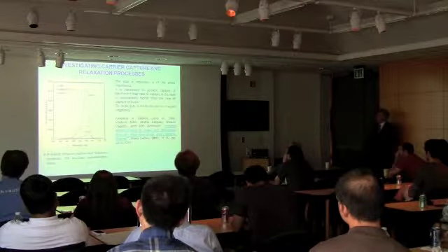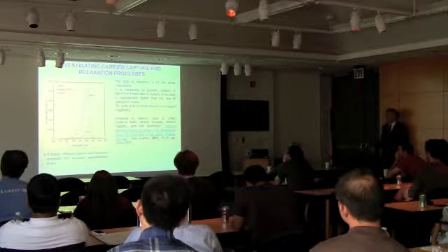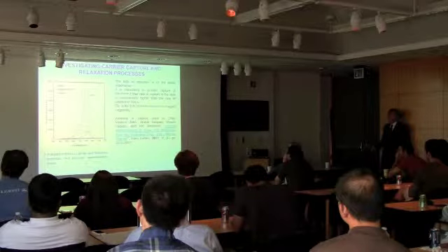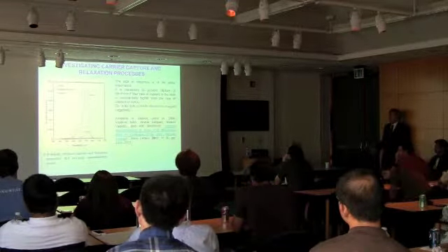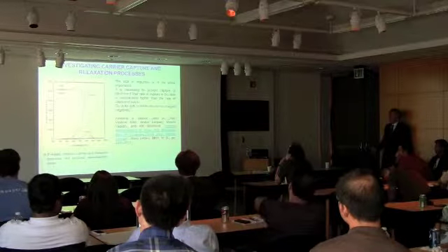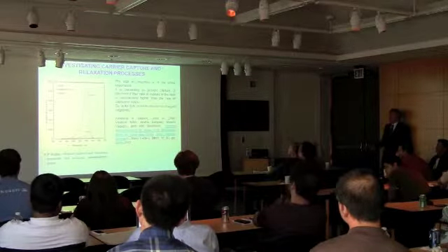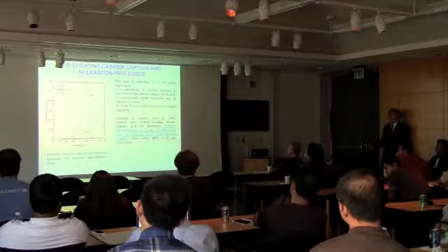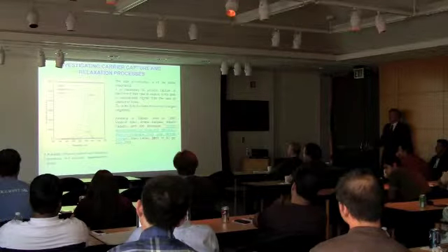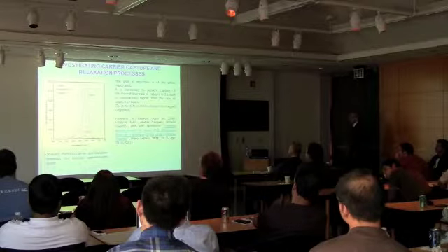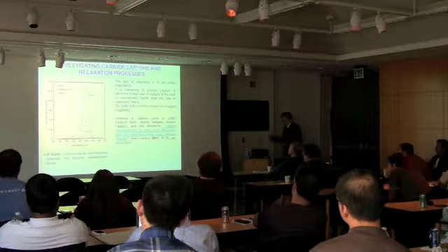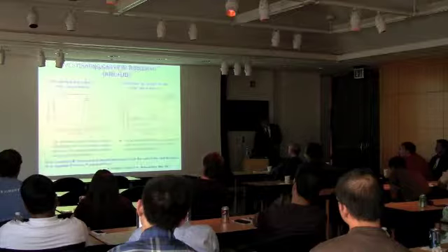Here it's the same level of doping. Exactly, we introduce 3 electrons or 3 holes per dot, and as you see, we have n doping. Then luminescence from quantum dots is about 6 times lower or 8 times lower than if we introduce p doping. So p doping, or no doping, is also bad, but p doping in particular shows deterioration